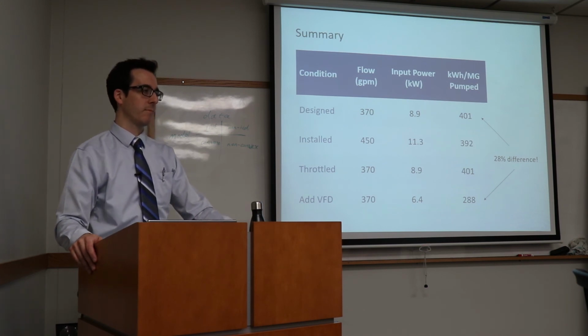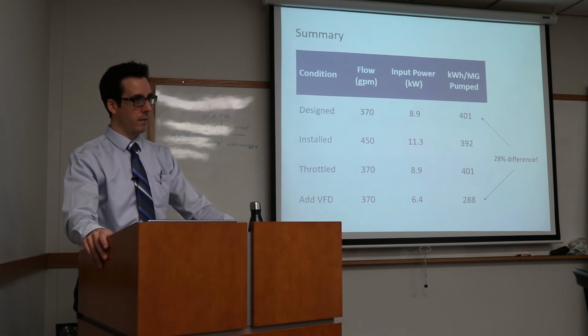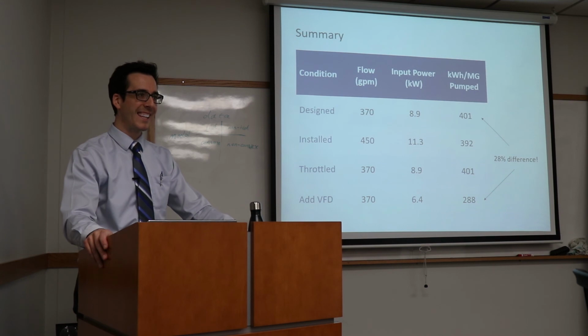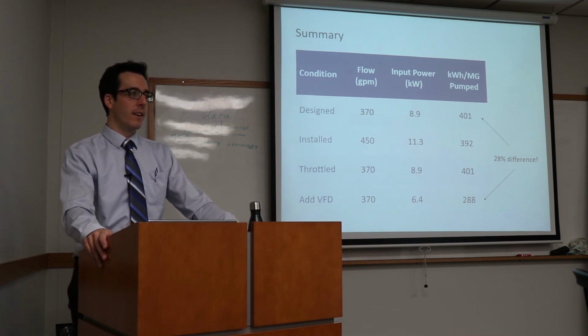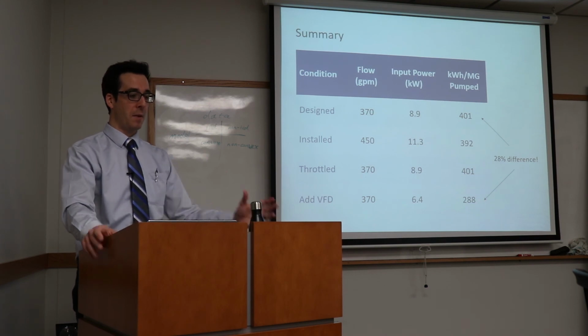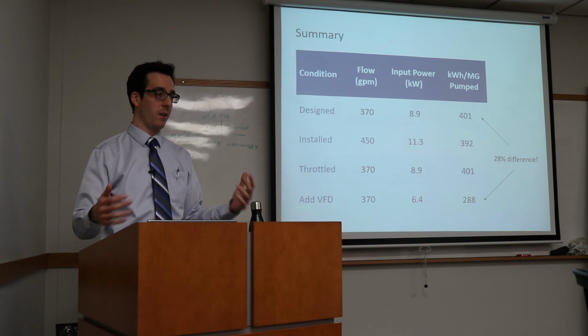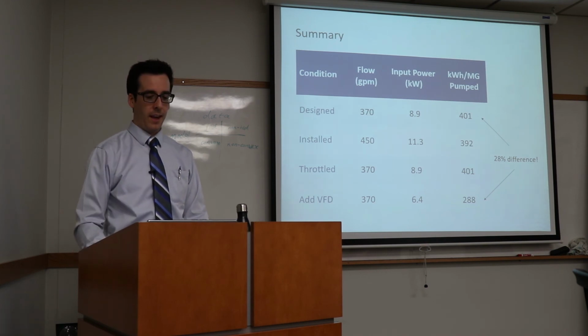Would you recommend getting many different sized pumps or a VFD to manage demand? Again, it depends, but VFD is usually what I see. Having multiple pumps takes a lot of space and a lot of cost. But if you really have a big range, sometimes the VFD can't cover a range of a factor of 4 or 5 on the flow rate, but multiple pumps can. Good questions. Okay, thank you everybody.